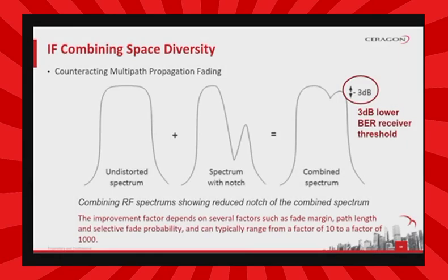The two receiver antennas will receive signals with different delays. As a result, if one of the two receivers should get a signal with a frequency notch, called distortion, it is very unlikely that the other will have a notch at the same time. If we then combine the signals received by the two antennas in phase, the spectrum notch will be significantly reduced. When a spectrum notch, or selective fading, appears on only one of the signals, the notch in the combined signal will be significantly reduced at this point.